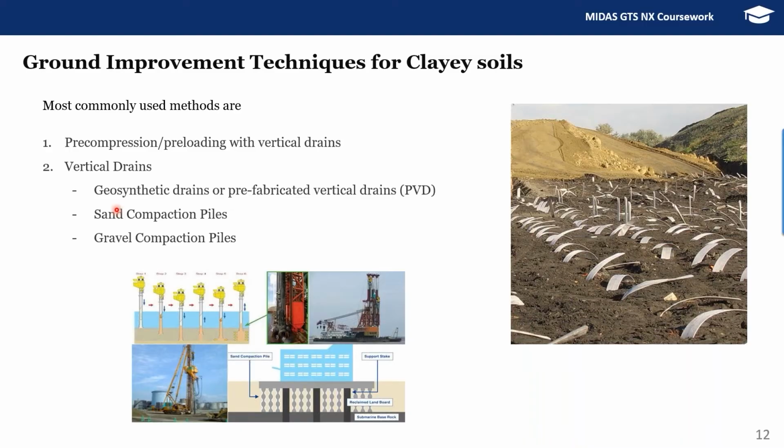The important ones are PVD, or prefabricated vertical drains, also called geosynthetic drains or band drains, or PBD. And then we have sand compaction piles or gravel compaction piles. Based on the necessity and the requirement, we can choose any of them.